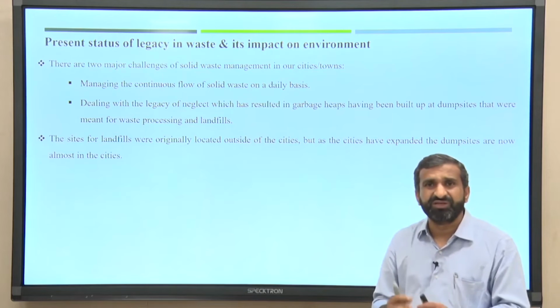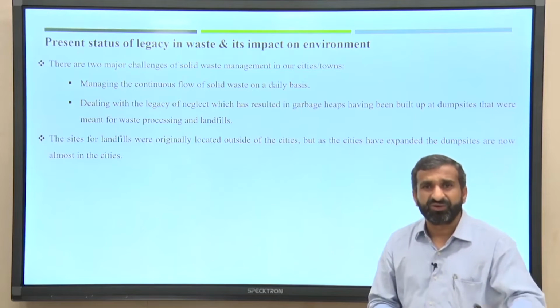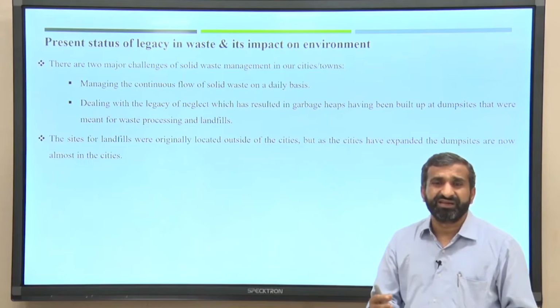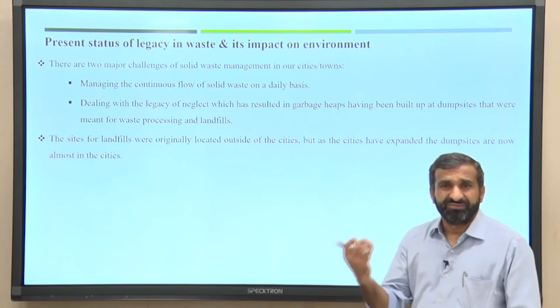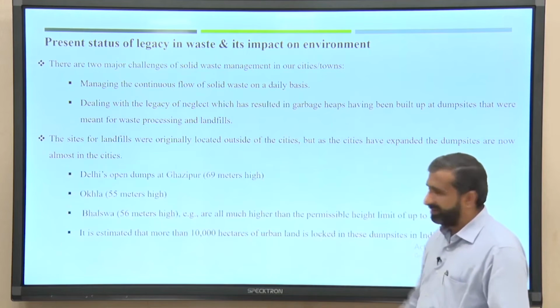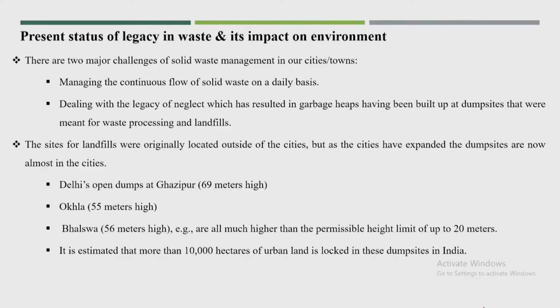Now it is a very big issue for the local authority or local corporation: how best they can recover that particular location, or dispose of that legacy waste in some other area. I have some data, like in Delhi, the open dump at Ghazipur has a maximum height of about 69 meters, Okhla 55 meters, and Bhalaswa 56 meters. All are much higher than the permissible height limit of 20 meters. And they already occupy an area of 10,000 hectares of urban land.